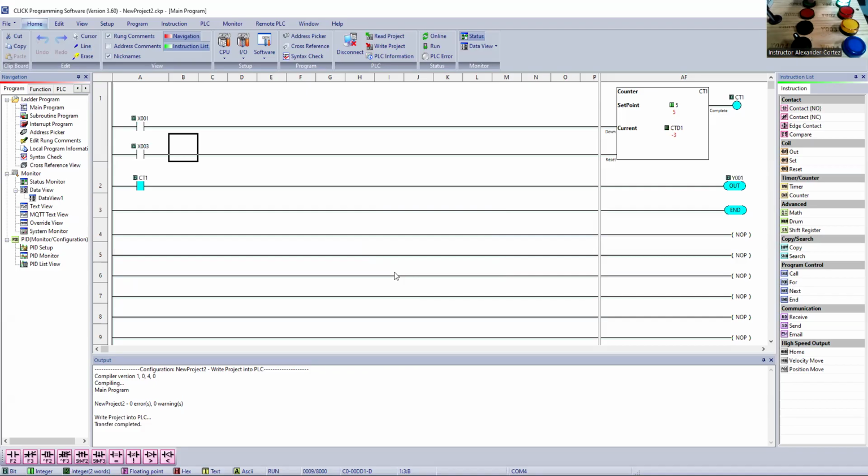So this would be used if, let's say that you're getting your set point from some other type of input device. Maybe it's counting how many times a bottle is put into a box. And once it reaches 12, then it goes into another process. But let's say that it finds a bottle that's broken, right? So then it can count down. So then it can keep track until we get 12 bottles that are good. And then once you get to 12, then you can move it on to a next phase.